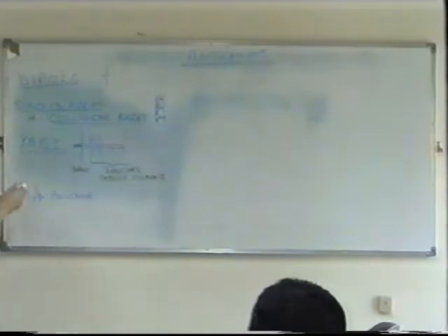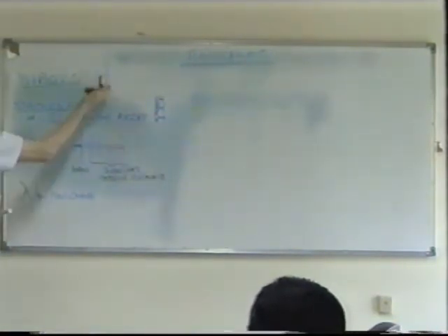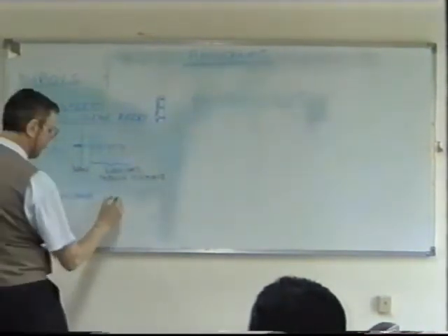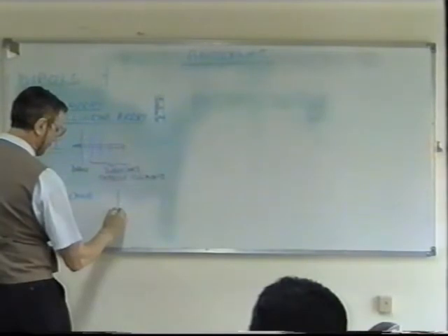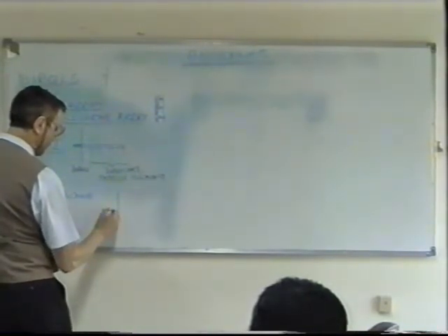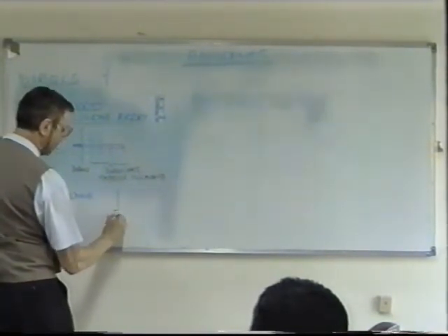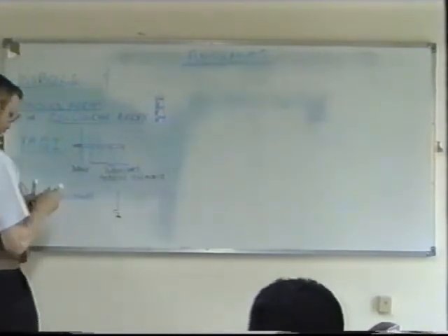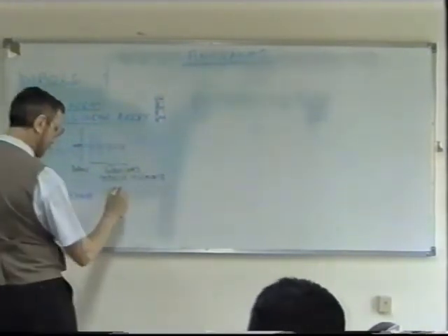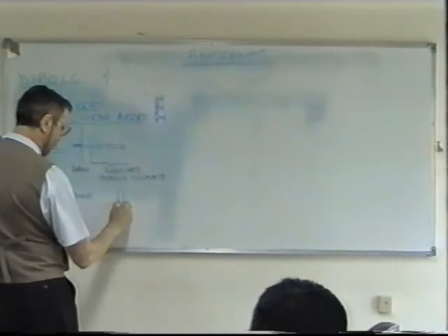Now, the quarter wave works in the same way as your dipole, except that one of the sides of the antenna is not needed because we use the ground. So basically this would go to the input and the other input would go to ground. And this here is only a quarter wavelength long, isn't it? This part here is like half a dipole.